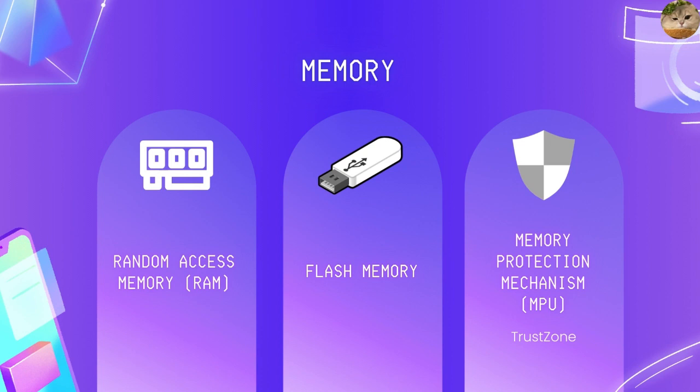So MPU, also known as a memory protection mechanism, is a hardware feature which divides memory into distinct sections and makes sure that a process is only able to access the memory that is allocated to it. This protects the system from malware and other malicious acts by preventing access to and modification of the memory of another process.